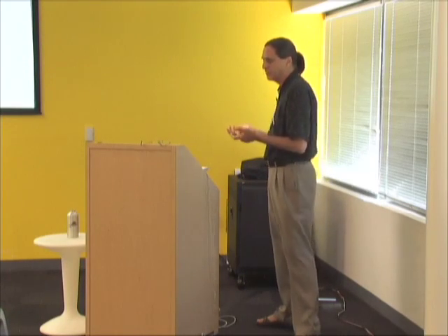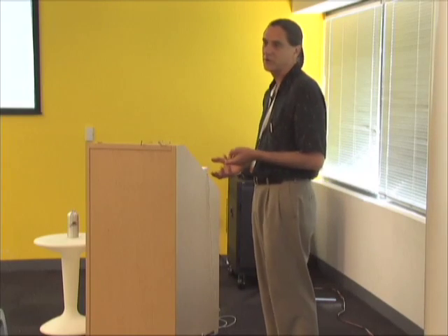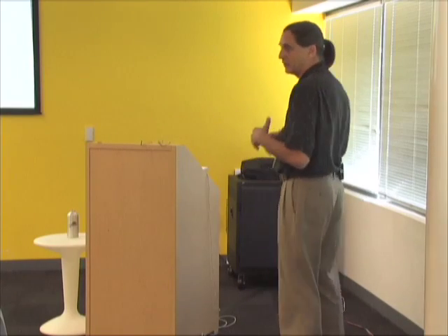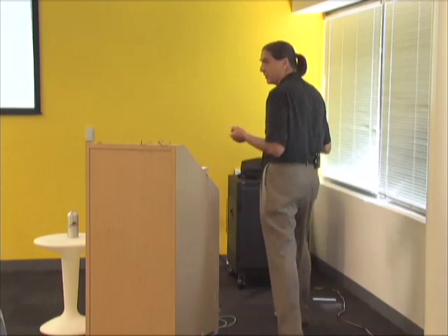There's no silver bullet in any of this, but you've got to use these things to isolate geometry and to organize it so you can essentially turn the geometry off when you don't need to see it. Don't look at things you don't need to look at when you're working your models. And if you make a big model and it's all on layer 0, you've not grouped or made components of anything, you'll never be able to do that. I mean, you can hide to your heart's content, but you won't get down to what you want. You probably won't be able to find it. You won't be able to move through it. So you need to use layers.